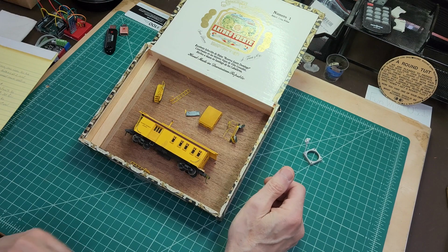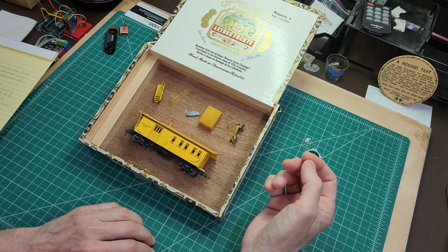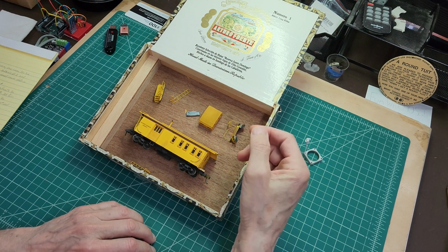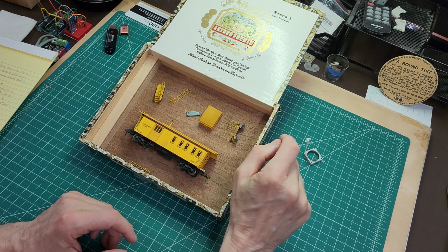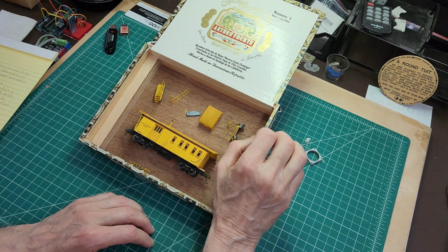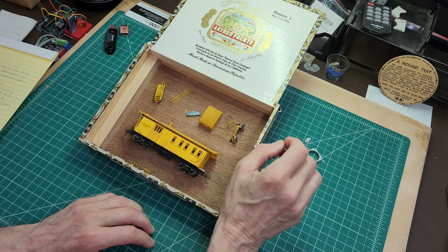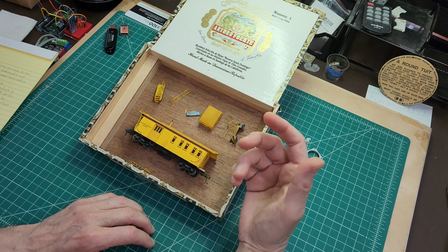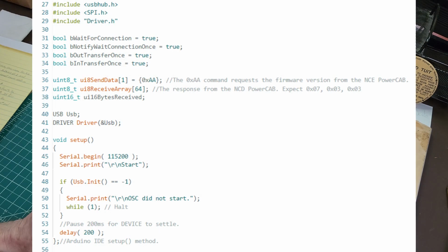As just mentioned, I have two USB drivers. One uses the two bulk endpoints at 2, and one uses a bulk out at 2 and interrupt in at 1. They're essentially the exact same code as I'm showing here. The driver object is declared as a global object here, and to conform to the library's requirement, I created an array of a single byte, AA, shown here, also in the global scope.